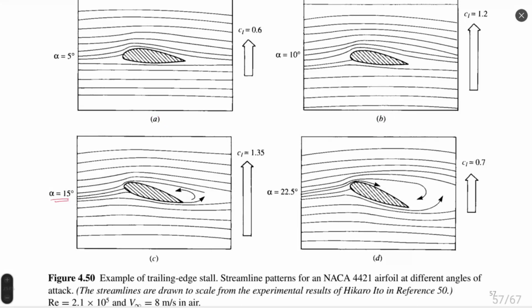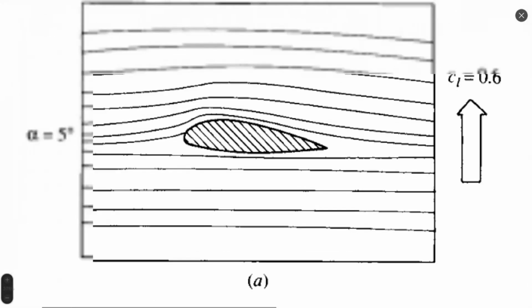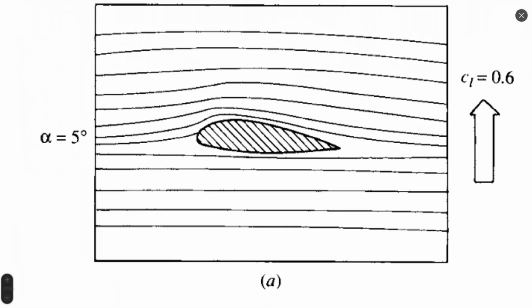It's more complex. I saw airfoils which have flow separation even at small angle of attack, even at zero angle of attack. Let's assume it's not 4412, but another airfoil. I saw an airfoil that even at small angle of attack already has a small zone of flow separation. It was proven not just numerically, but also experimentally.